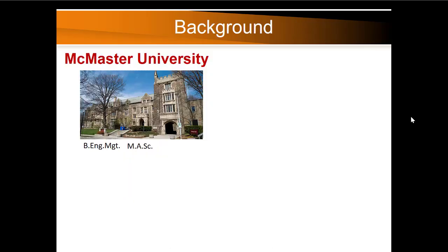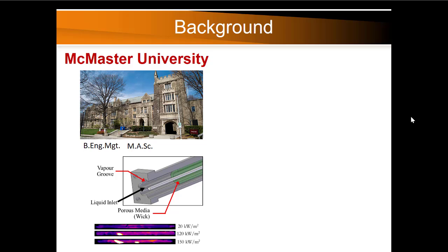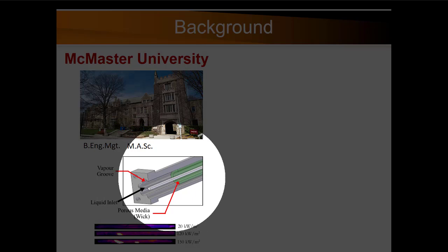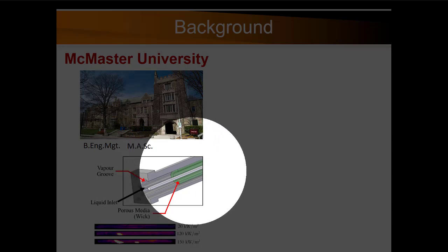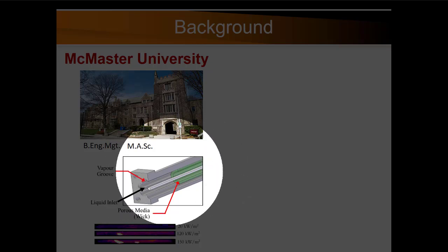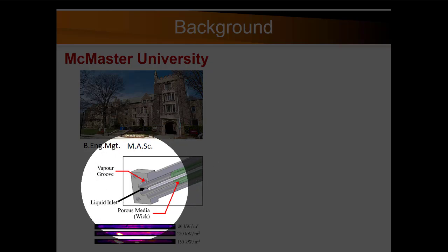For some of this, it's worth having some context of the path that I took. I did my undergraduate and my master's degree at McMaster University in Hamilton, Ontario. The topic of my master's degree was capillary evaporators in capillary pumped loops. Here we have a porous wick filled with fluid, and heated fins that come down towards the wick, and then boiling happens at the fins and the vapor comes out these vapor channels.